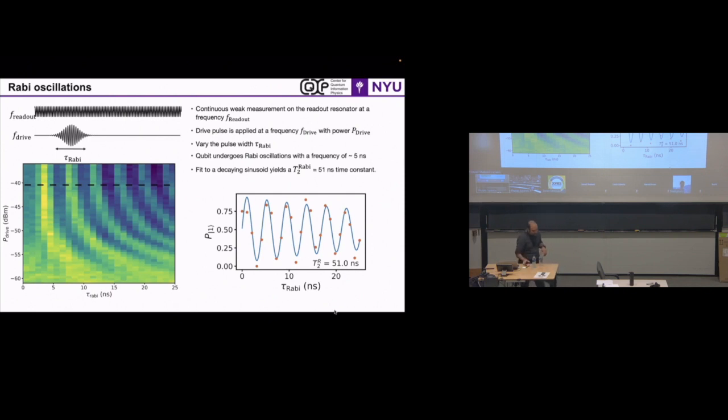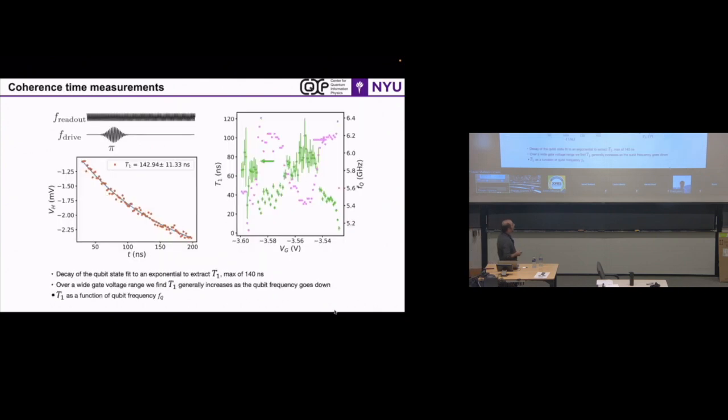Imagine I have, I don't know, the best 100 microsecond and 100 microsecond qubits, but I make a gate voltage tunable coupler in between. You can actually show theoretically that even if this coupler is really bad at this level of coherence time, it doesn't add much to or harm the fidelity of a 2-qubit gate. It's basically a bypass agent so that error doesn't come in. So I think that would be very, very interesting.